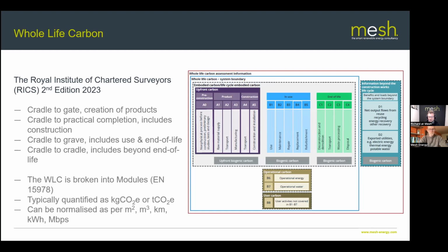So it's all the unregulated energy as well. The process that backs that up is a method called CIBSE TM22. That can either be done as a desktop study to understand operational energy, or if you're working with us, then we do a lot of dynamic thermal modeling, where that becomes a lot more involved in terms of occupancy profiling, time of use, and so on and so forth.